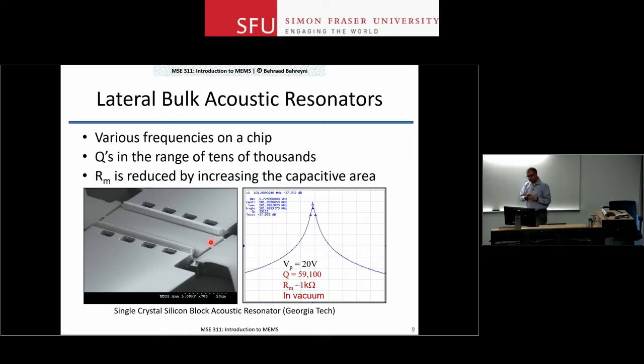One of the things about timing resonators is that you want to keep them as simple as you can, because actually a more complex structure with more damping, with more anchor points and things like that will usually lead to having more support loss in the end. So that goes against the idea of having a high Q. So most of the high Q devices that you see are super simple. It's just a beam, it's just a spring that is made of the simplest structure possible, right?